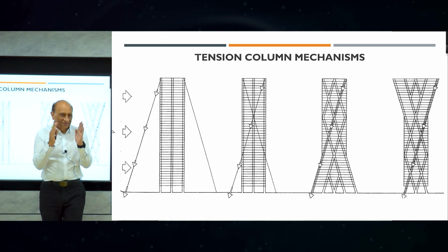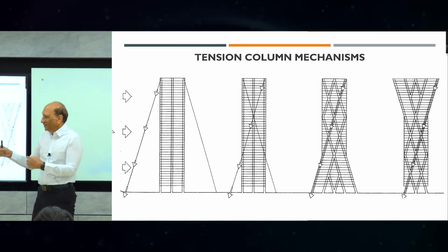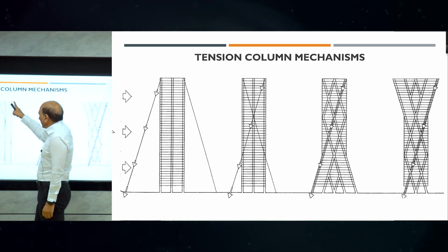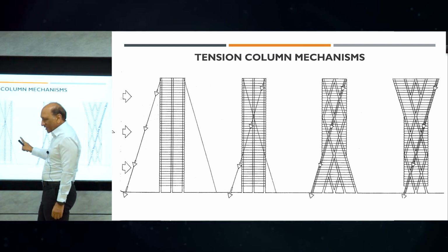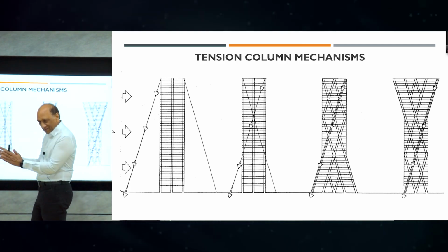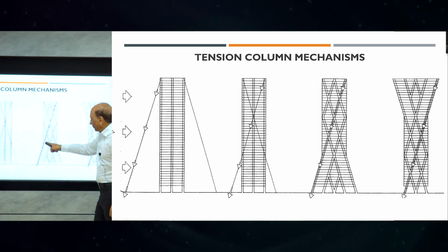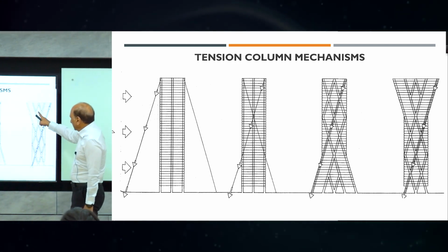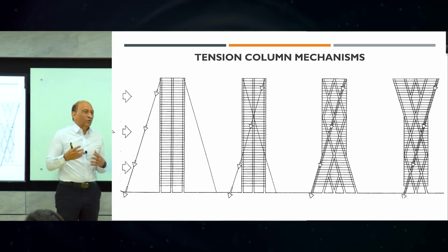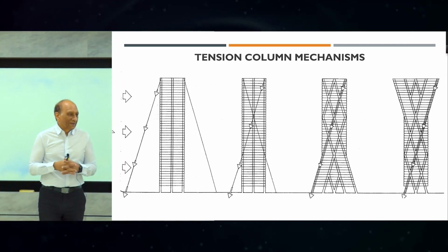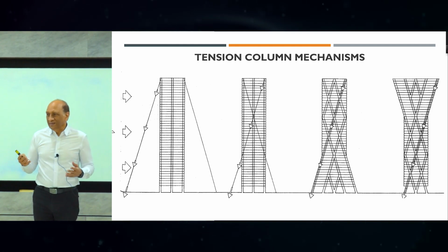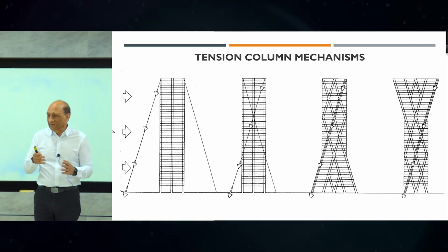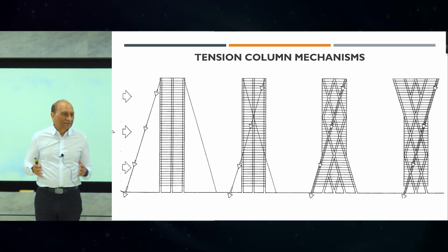Look at the architectural simplicity of the idea. Watch this carefully. So he put the cables first like this. Then to save the space, he moved the cables to the inside. So you get the same effect, and then modify the building to be internal bracing like this, concrete. So instead of cables, you use a concrete member, and then another way. People have followed all these concepts in building design because architects look at these things in this way. They develop the systems gradually from a simple one by altering, adding something and making it very natural. And then from there, form will come up.